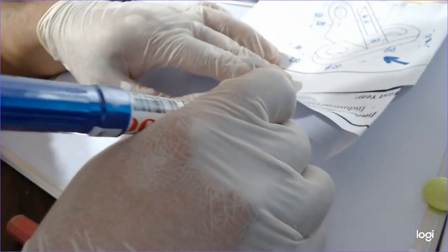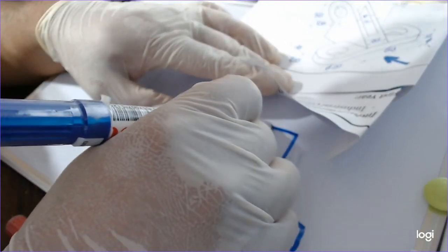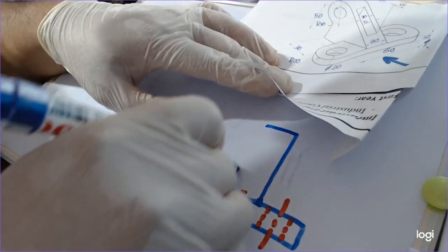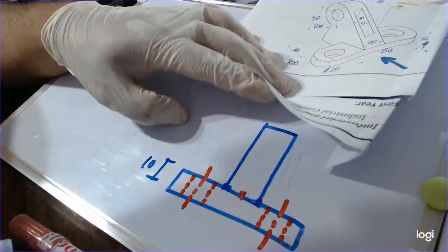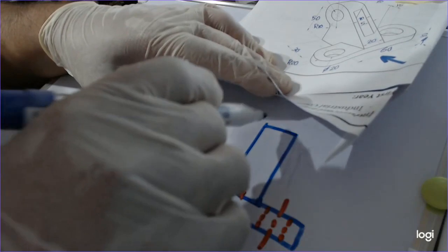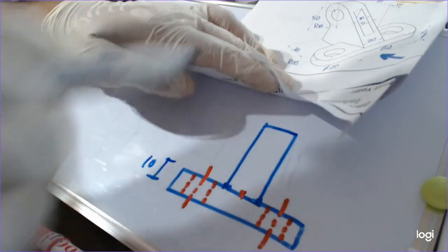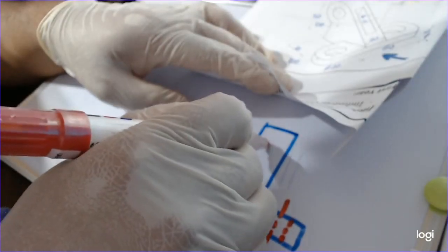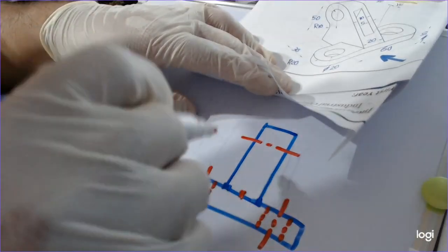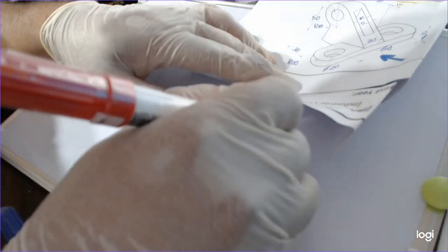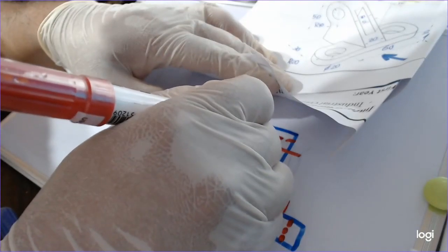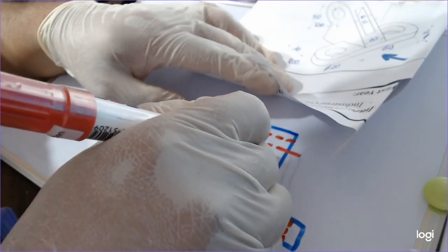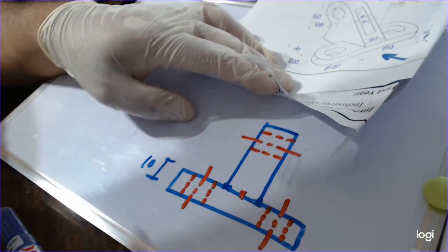Okay, go to the right, to the left 20 millimeters, and go up from here 60 millimeters. Then I will go down 20 millimeters and make a center line of the hole. Around this center line, I will go up for 10 and draw the hole. The same down here. Okay?